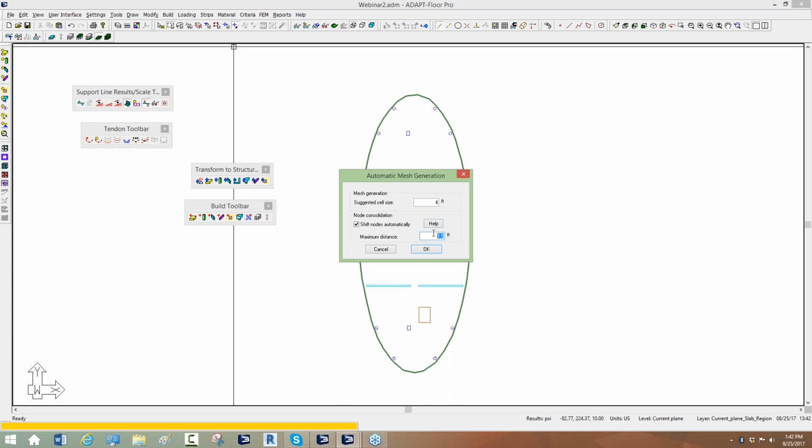What the program is doing is taking physical nodes and consolidating them into analytical nodes, where one node might represent a physical node of multiple components. So from an analytical standpoint, you're creating a substructure which has shifts in it which move the location of the end of an actual component that's modeled in the program.